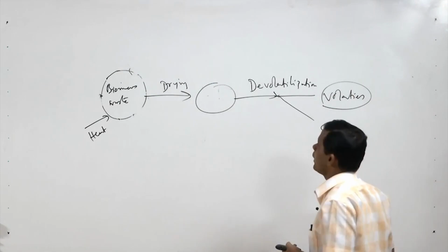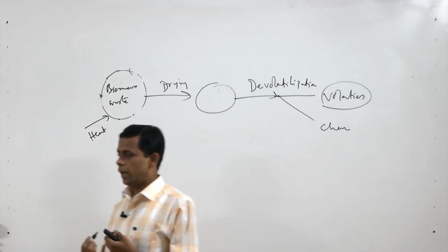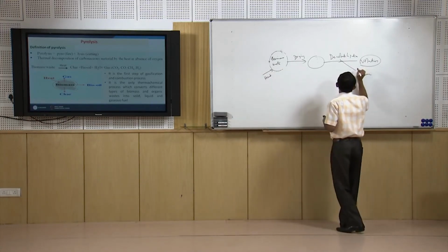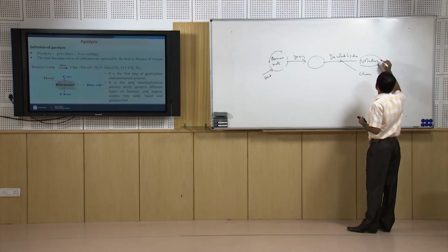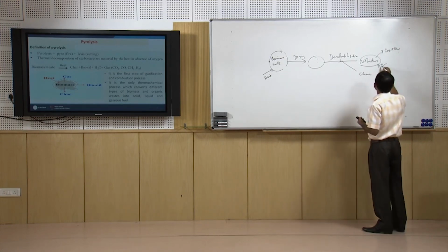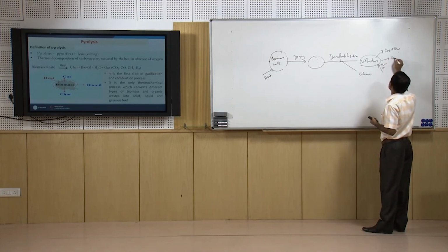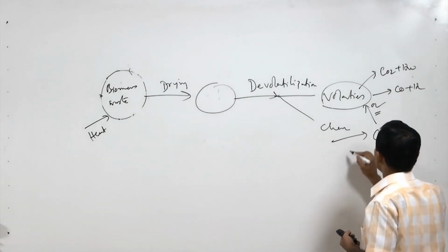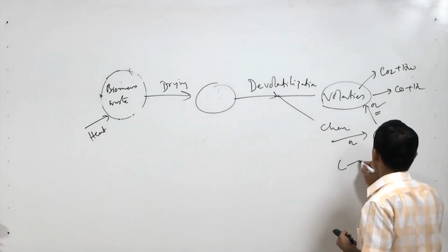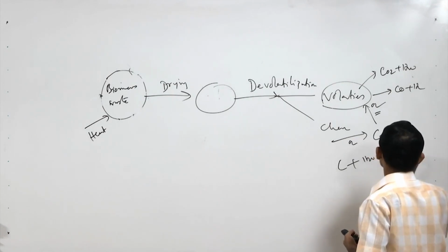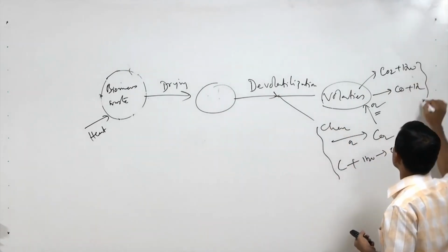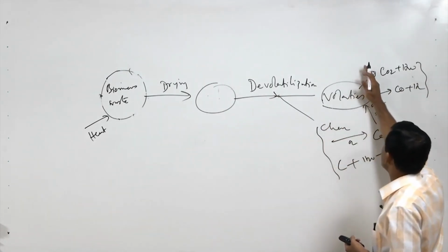These volatiles will contain many compounds: aldehyde, alcohol, acid, many things. When we put in oxygen, we get CO2 plus H2O; when we give a controlled amount of oxygen, that will give CO and H2, and then char is also oxidized to CO2 in the case of oxygen, while in gasification the char is converted to CO plus H2. These are for gasification and this is for combustion, but in the case of pyrolysis nothing happens here.